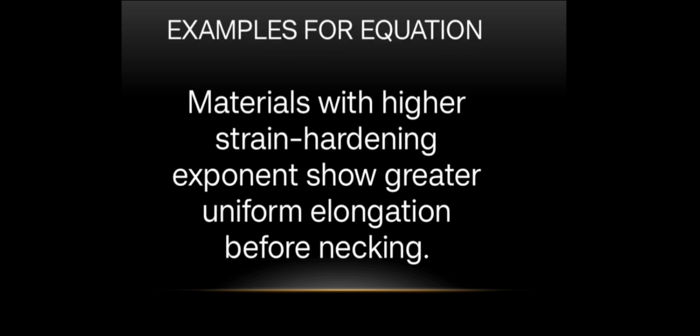In the earlier equation, we can use another equation, the power law formula σ = Kεⁿ. What I'm trying to say is that a material with a high strain hardening exponent shows more uniform elongation before necking.